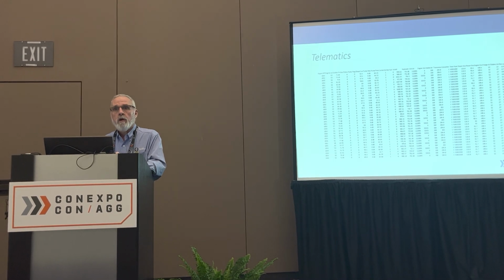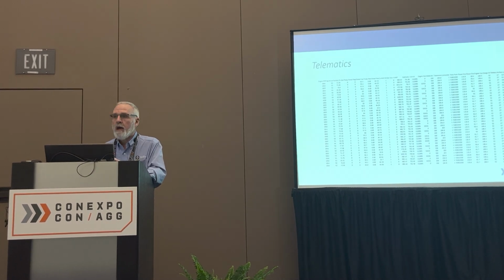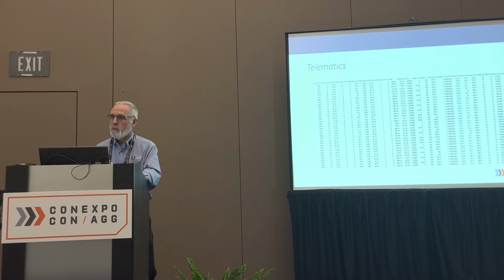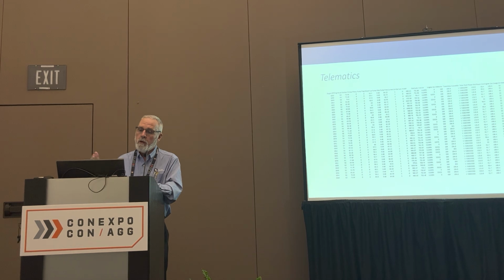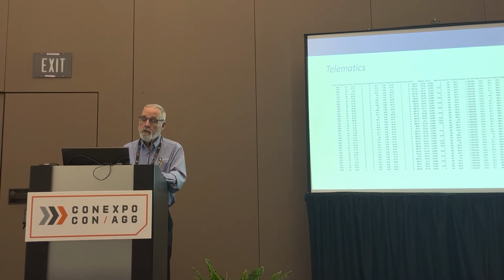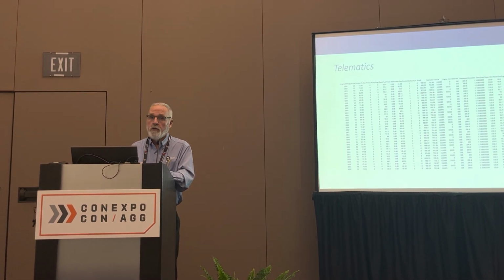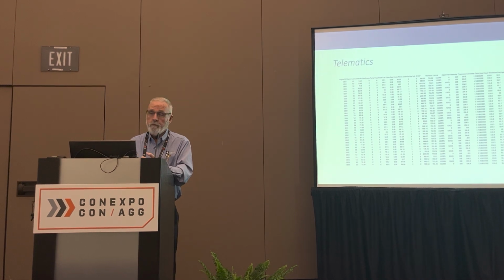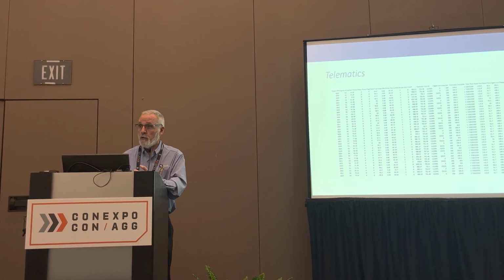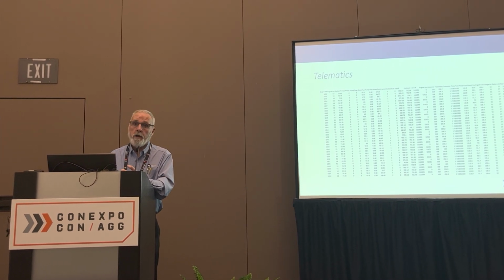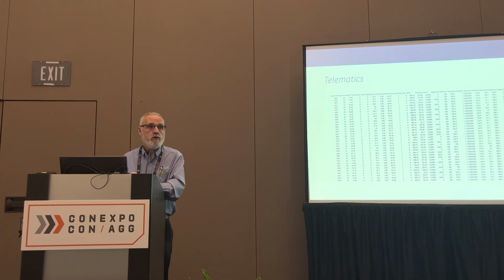I had reached out to one of our customers when I was first dabbling with this to see how much telematics data would be of value to our data analysts, because there's some relationships there. To give you an example, we had a customer that kept sending in samples on the same component. It was a diesel engine, and it kept coming back as fuel dilution. Now, as a data analyst at the laboratory, we could flag it high severity. We could tell the customer in the text logs that, hey, there's a problem with fuel dilution in your oil, and we recommend you check A, B, C, D, and E for the cause of fuel contamination.